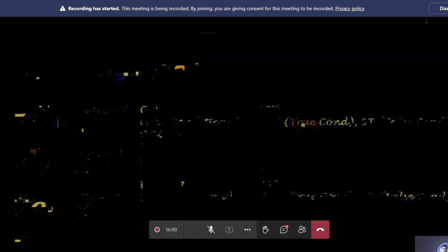Yes, sir. And sometimes it might happen that the zero flag is not set, but the CZ statement has something written after that. So call on zero and there is some address. But since the zero flag is not set, that call will not be executed fully, right? Because the condition happens to be false.